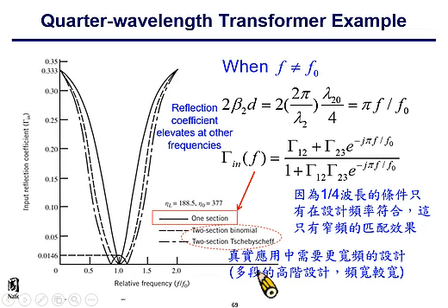Let's go to this slide. This is the so-called binomial design. It touches the matching point at the required center frequency once, and the bandwidth is broadened with higher order design.